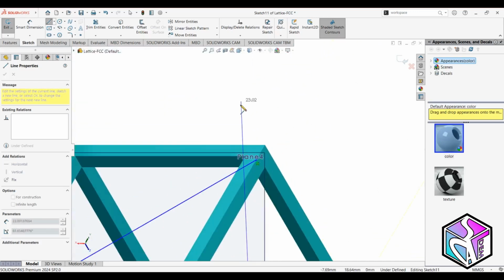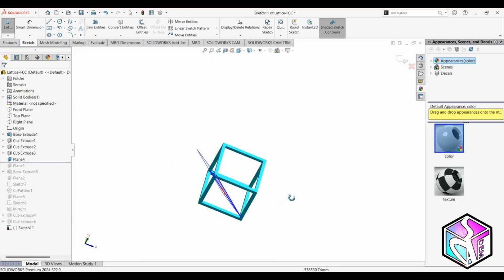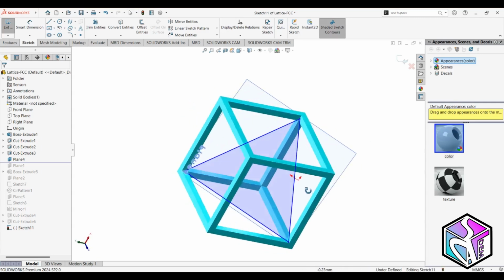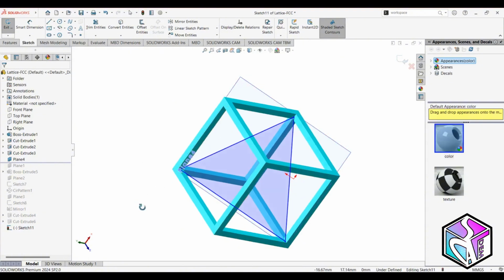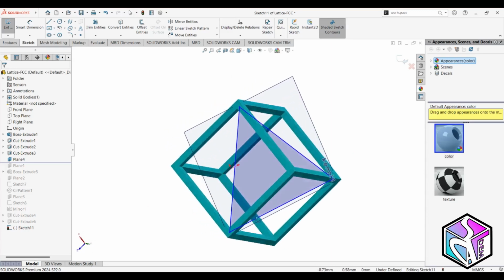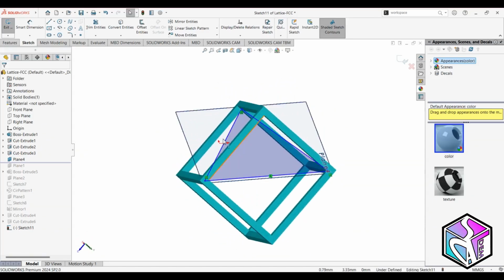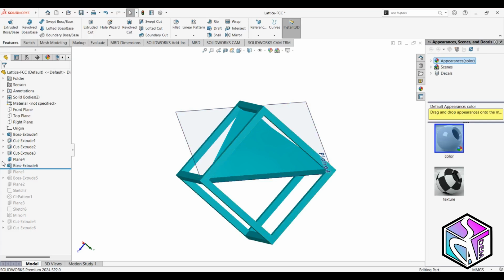Okay, it's a little complicated at the first stage. Let's just see that we choose the right angle of being normal to this plate, because if we just normalize from this view port, you could draw the wrong plate, but now we are clear and now we are good. We have created the right geometry that we wanted. So let's just extrude this plate for 1 millimeter mid-plane unmerged, and okay, let's just hide this plane to see what we have drawn.